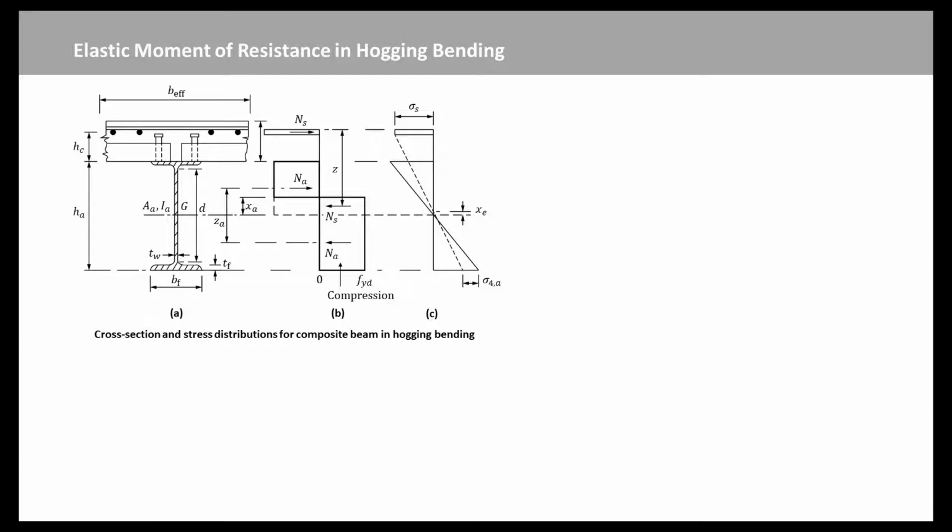Where elastic section analysis is used, creep is allowed for in the choice of the modular ratio N equal to EA over EC effective, and so has no influence on the flexural properties of cross-sections with no concrete in compression. In buildings, the effects of shrinkage and temperature on moments of resistance can usually be neglected, but the method of construction should be allowed for.